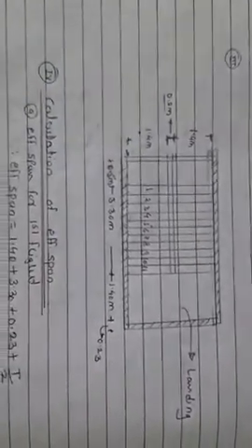Now here you have to go for the arrangement drawing for this staircase. So size of the stair room is given as 3 meter and 5.20 meter. So here we are assuming the clearance between these two flights as 0.2 meter. So this clearance is considered as 0.2. Then the width of each flight, so this is the width of your first flight, which is equal to 1.4 meter, and width of the second flight is also considered as 1.4 meter. So total this 1.4 plus 0.2 plus 1.4. So we are getting 3 meter as the width of your stair room.